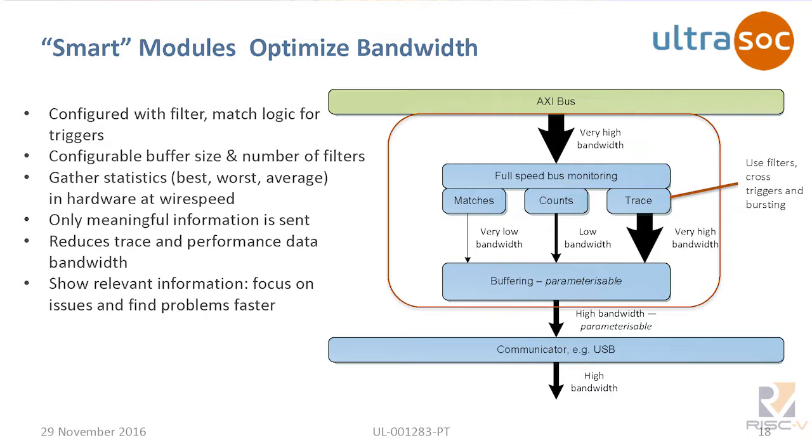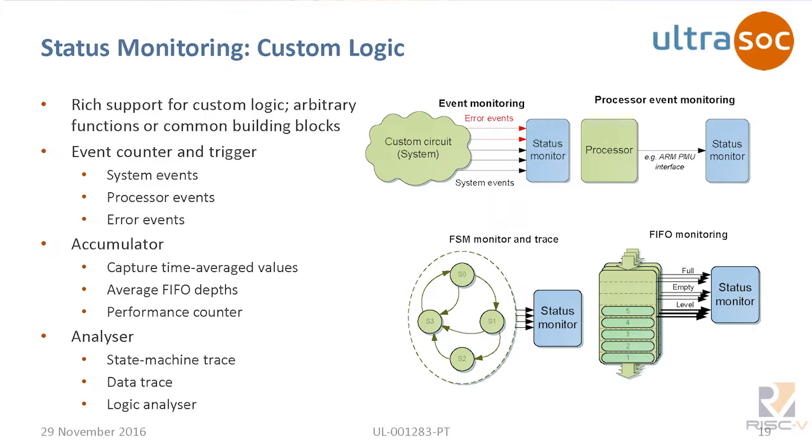So for certain parts of the chip I showed just earlier, you'll have a slightly less rich bus monitor as opposed to the dual ported bus monitor by the DRAM controller. You'll have the knobs set up higher. The status monitor takes in general generic signals, and you can set at runtime what those signals mean and what to do. So let's run through one example.